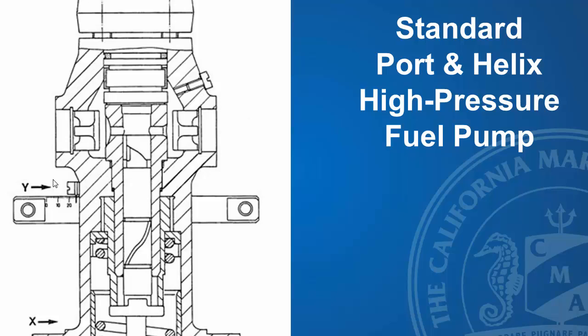So one of the things that needs to be discussed is that this 25,000 psi, or 1,500 bar fuel, is being dumped back into the suction line. So you have a suction line that is supplying fuel to the pump at typically about 8 bar. All of a sudden you're dumping 1,000 bar fuel into that suction line, and that can cause pressure pulsations in the suction line.